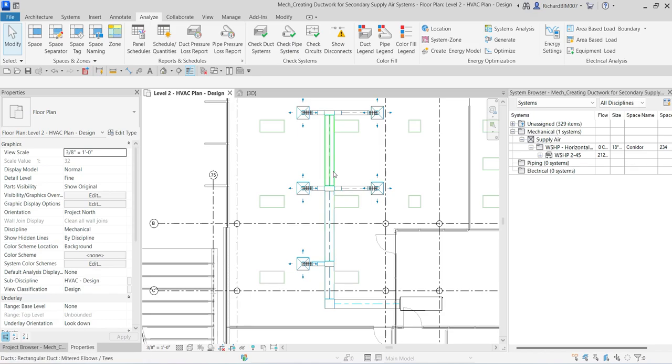There you go. So there's no issue. There is no error, because if there's an error, there's usually a message that will pop up somewhere here. Okay, so now there's no error. Errors may occur while attempting to create the duct geometry as a result of converting a layout or during sizing. The most common cause of these errors is that the duct has insufficient space to be created, or offset elevations are incorrect.